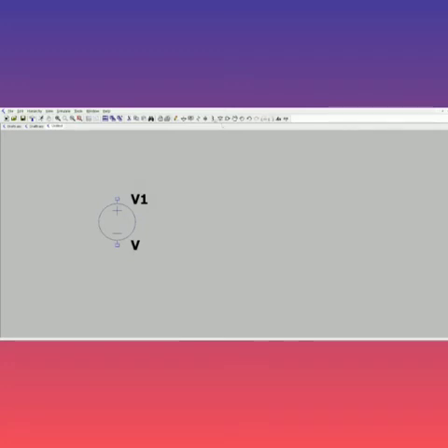Then take a capacitor. So you want the capacitor to be turned. So I'm giving Control R so that it rotates, placing it like this. Next, I require a resistor. I'm placing the resistor. So next, I want a diode. So click the diode and place it here. So here I'm going to do negative clamper. So my diode should be faced like this and I'm placing it here.